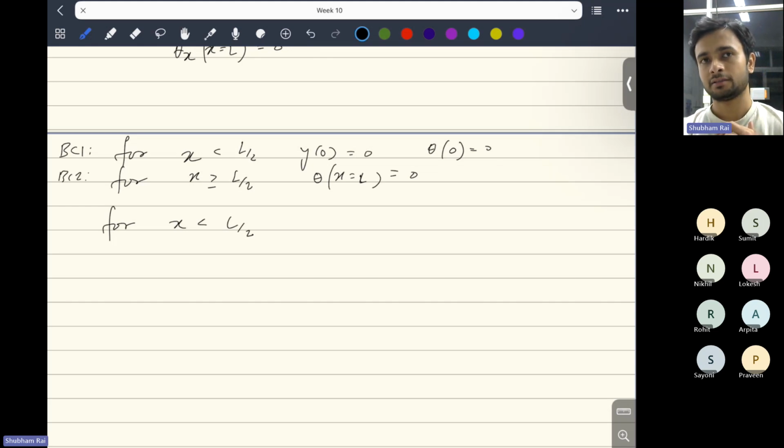And when we write the stresses, we treat it as bending moment. And similarly with the shear force. When we write it in stresses, we say that shear force acting on a positive x face in the positive y direction will be positive, and on a negative x face in the negative y direction will be positive.